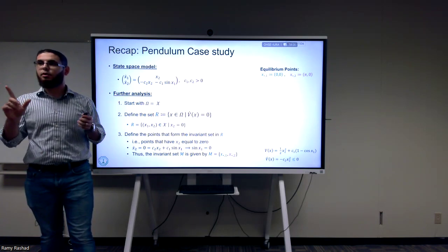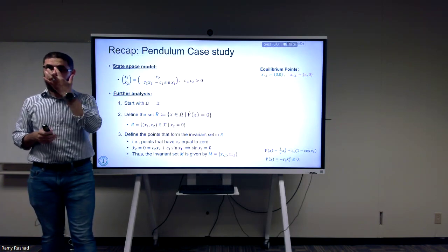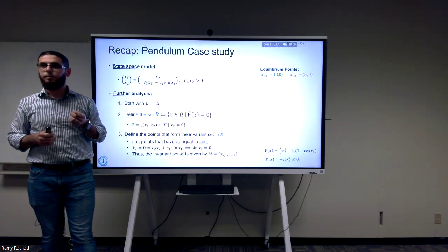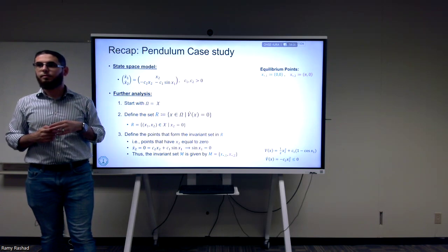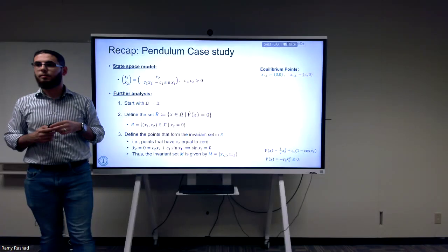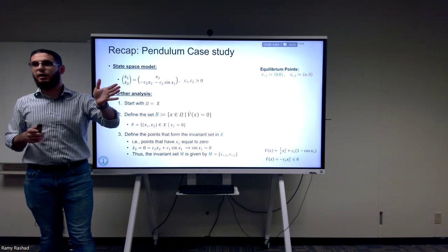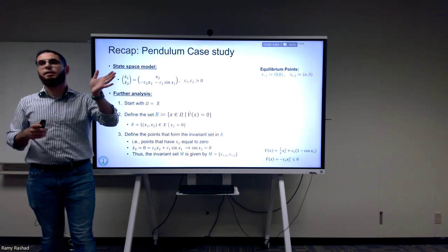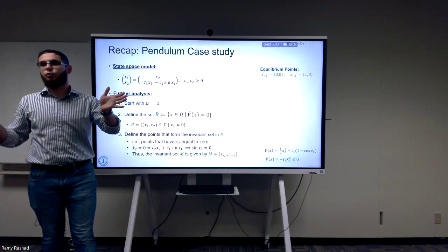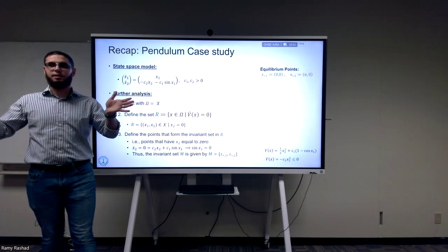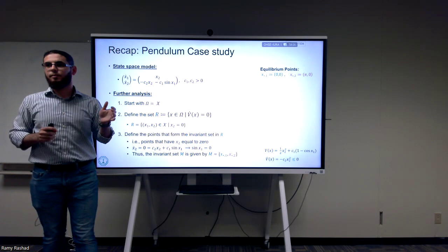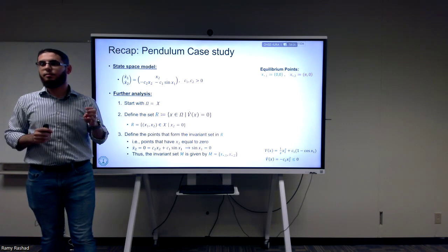Yes. Exactly. Okay. So now we know it's stable, but in terms of stability, we have how many options? If we were to go deeper, how many options would we have? A lot. Not just stable, asymptotically stable, and not just local asymptotic stability and global asymptotic stability. You have much more than that. Exponential stability and finite time stability. But then exponential stability is also a form of global stability.